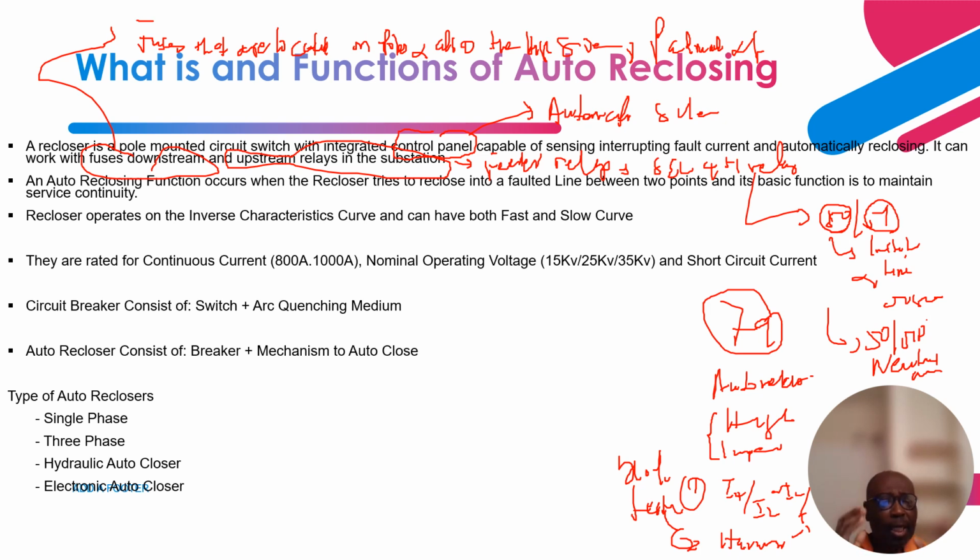But if you maintain a recloser in the middle of the radial feeder, it means that not all the 300 or 500 customers are going to be without power. Only a fraction of them, let's say 100 customers, are going to be temporarily without power due to the open and close action of the recloser.